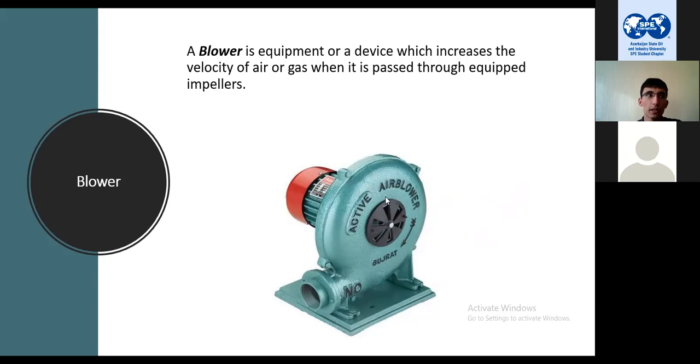in order to transfer our product. At the end of the section, I will show you the photo of polypropylene pellets and polypropylene powder. In order to transfer them, we use air blowers and nitrogen blowers to make them flow inside the pipes for transferring.